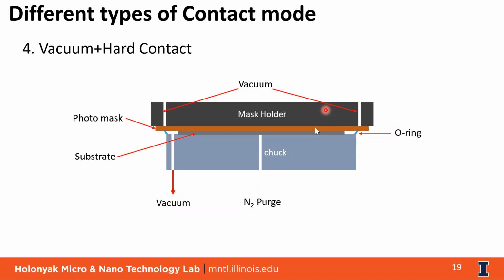In order to use any transparent substrate, usually you can control it along with your baking and the exposure. So you can have a little bit extra soft bake and you can reduce your exposure duration a little bit. So by varying your soft bake and the exposure, you can get better features in the transparent substrate.